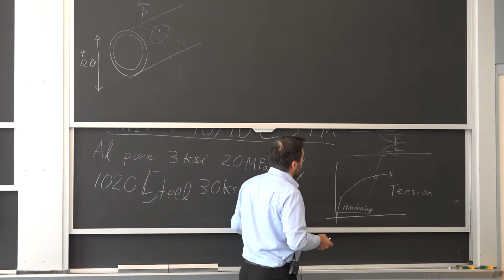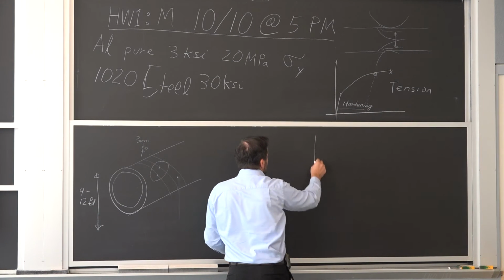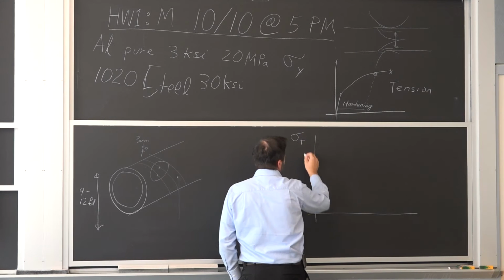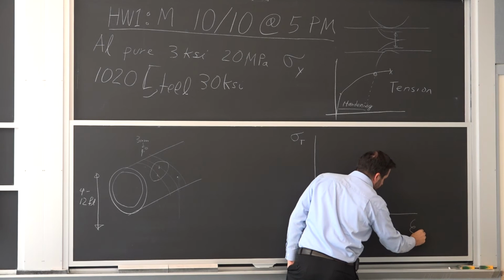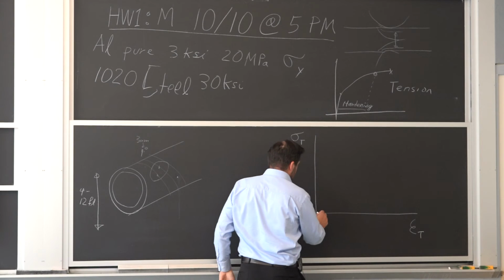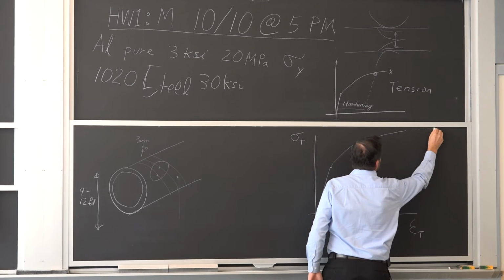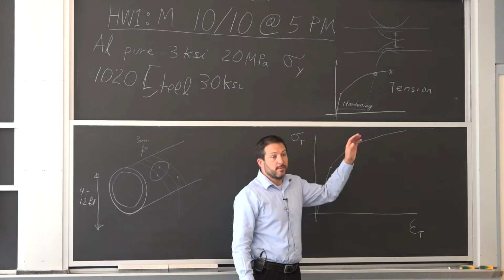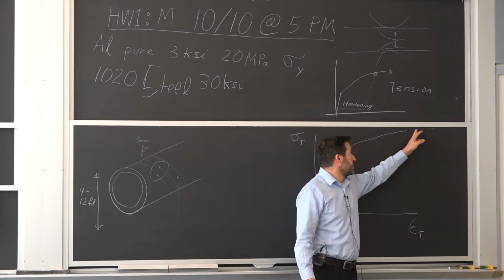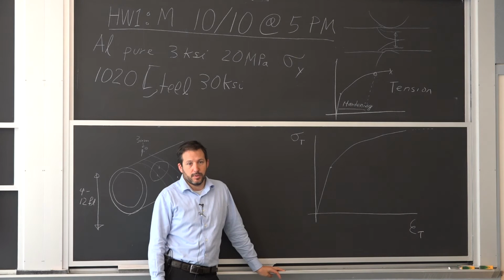Yeah, on rolling, what happens is, if you look at a true stress, true strain behavior, the steel never really gets softer. The only thing that happens here is it necks. So if you do it in compression, because you don't get the necking, it kind of looks like this, and it keeps going, and eventually it almost stabilizes, but it never goes down especially at ambient temperature. And before you reach this point, you're at somewhere in the order of 200-300% of deformation. Very good question.